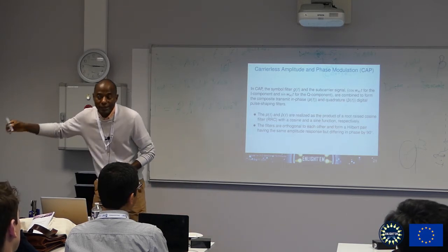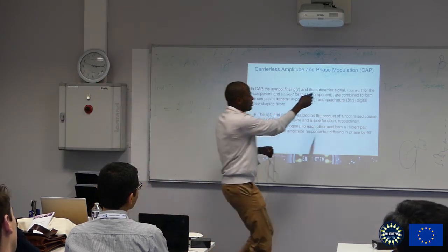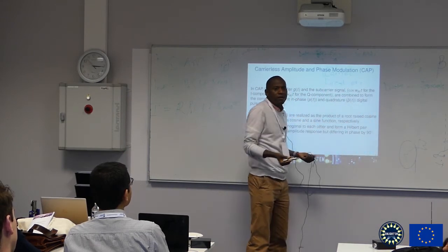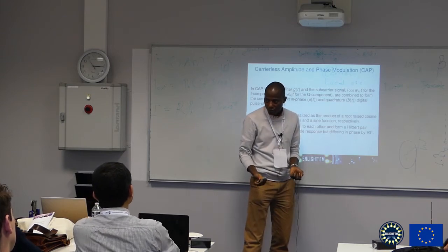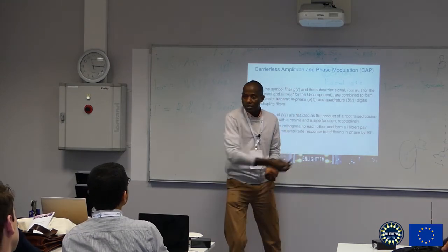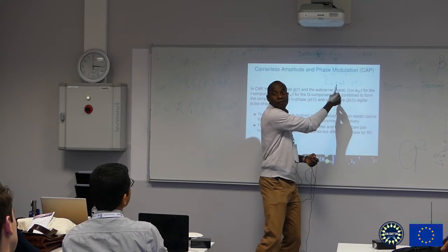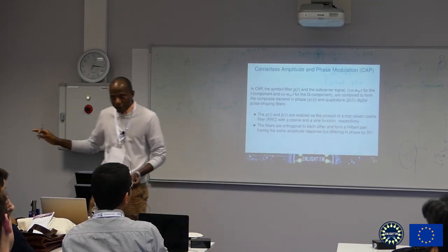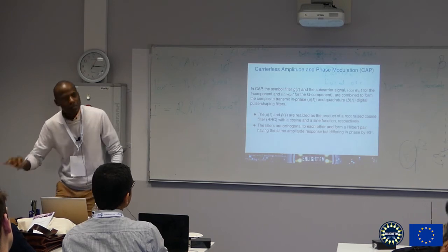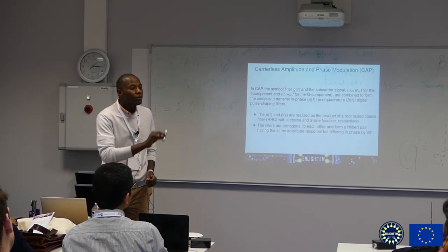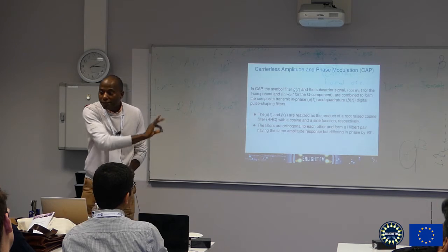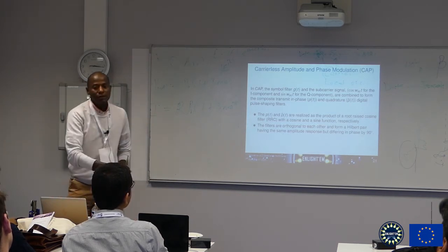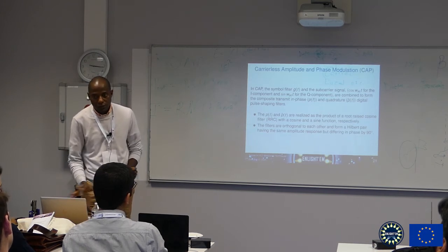It's just about simplicity. This ordinarily would be a local oscillator. You understand? But I don't need that high frequency. So I can just use a filter to design a cosine wave or a sine wave and then multiply them with my root raised cosine. And that's the only difference between a CAP and subcarrier intensity modulation. Every other thing remains the same. It's just that we don't separate the carrier and the pulse shaping filter. That's all. That's the only difference between them.